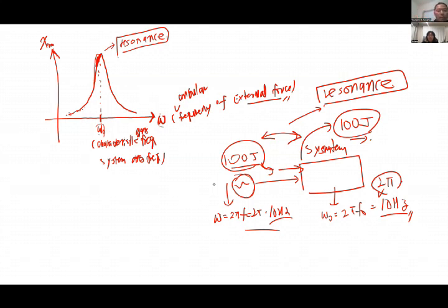The bridge was swung by the wind, and it turned out that the frequency of the wind was exactly the same as the system frequency of the bridge, so all of the energy of the wind was transferred to the bridge, and the amplitude became bigger and bigger and bigger. At some point it went beyond the structural threshold and the bridge suddenly collapsed.